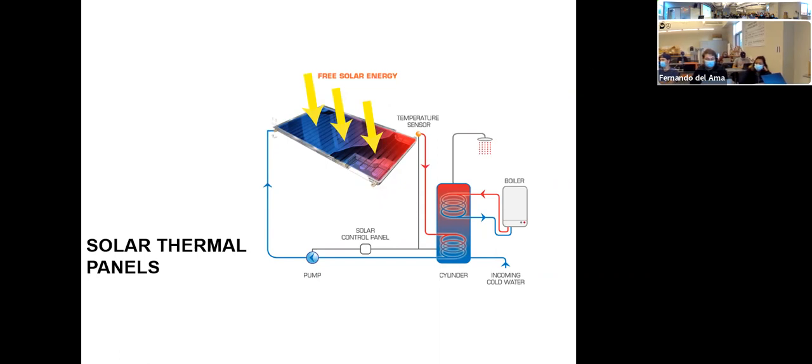Okay, there's a tank here. So from the top of the tank, we need the hot water supply. Okay, so we need the hot water supply. This can be the shower. And the temperature here in the domestic hot water should be at least 140 Fahrenheit.